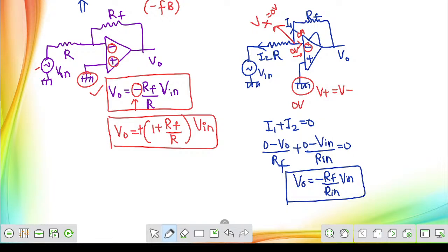It doesn't matter what type of circuit they are giving. All you have to do is apply the concept of virtual grounding with a negative feedback. Cross check whether negative feedback is there or not. Then directly apply the concept of virtual grounding, and always remember in an ideal operational amplifier the current consumed by the op amp is always equal to 0 ampere. Remember only these basic things and apply, you will be getting the answer. I'll show you one more example also if you want. Wait.